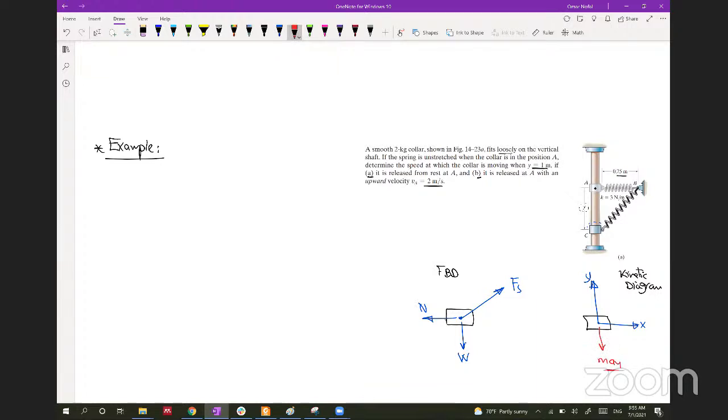So this is m a y, and then you solve the problem using Newtonian kinetics. But what is required here, and I think it's better because the velocity is given at the initial and final locations, is this: knowing the mass of the body, you can get the kinetic energy at the starting position and at the final position. That will help us.